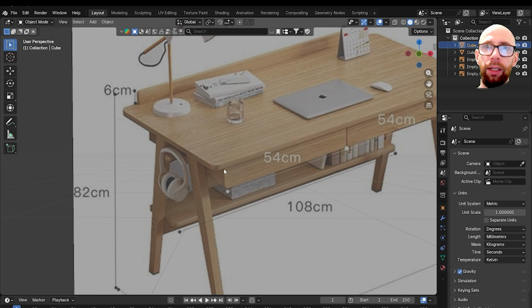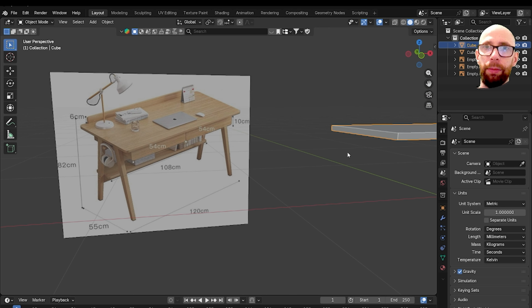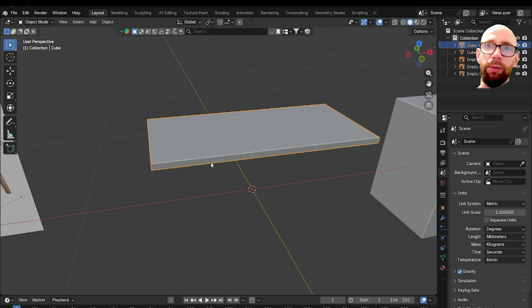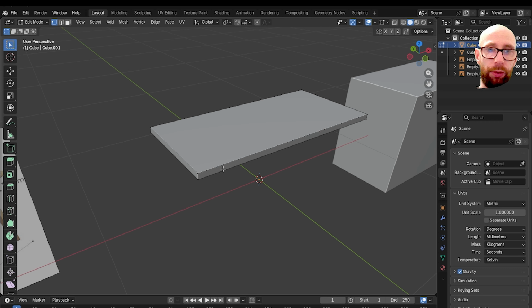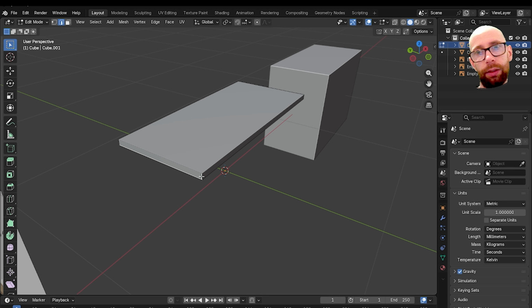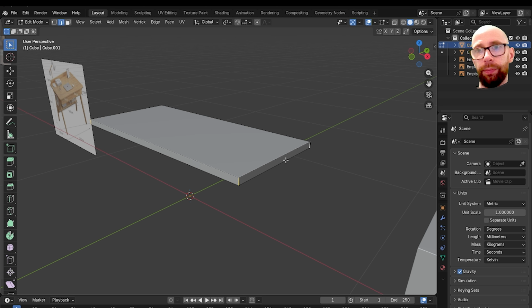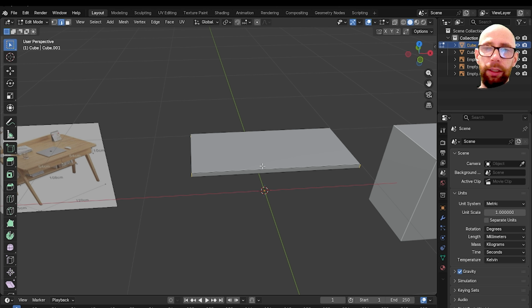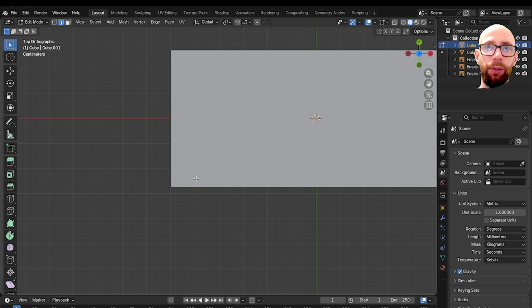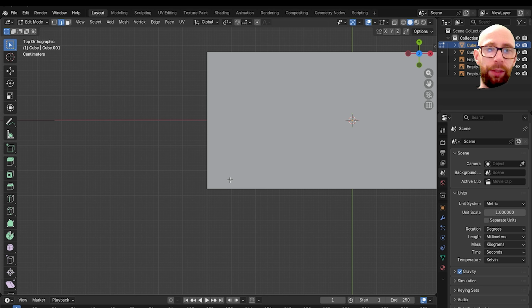Now, if you look here, you've got some rounded corners. Okay, so we want to add those into our shape. I'm going to hit Tab on it to go to edit mode again. Press 2 to go to edge mode, or you can click up here and grab these edges, the corners here, like that. Now, to round off those edges, the keyboard shortcut is Control B, which is for bevel. So I'm going to go Shift B, Control B, and click.